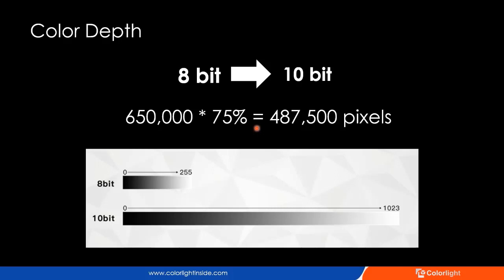In our system, when the video color depth is increased to 10-bit, the loading capacity of each output port is 75% of the 8-bit.